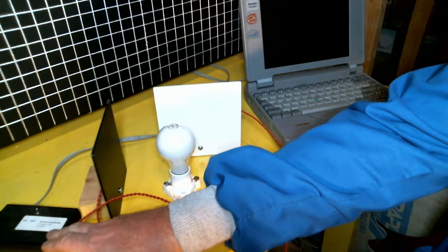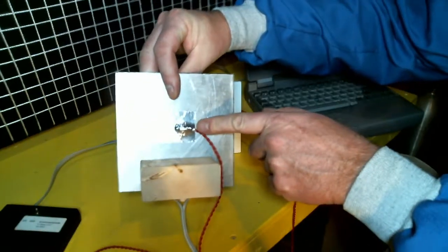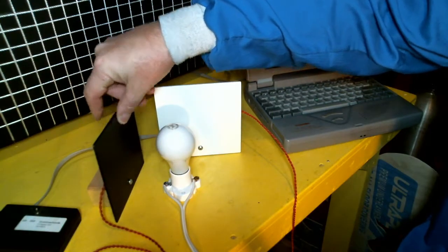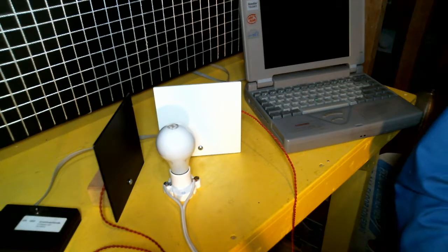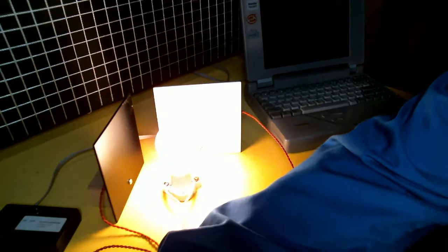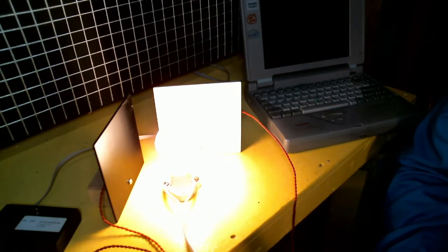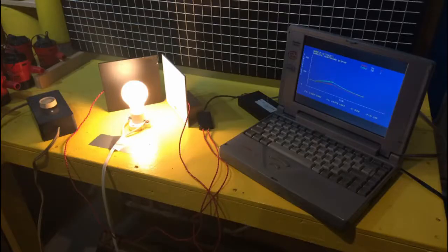Now, I've got a little electronic measuring device. In the back of each of these plates, I have a thermistor attached. So I can actually measure the temperature of the plate as a function of time and display it on a computer, and then analyze that data. Now again, when I turn on the light bulb, things start heating up, and I can measure the temperature every minute or so and see how the temperature of the plates progresses over time. Now here's my setup once again.